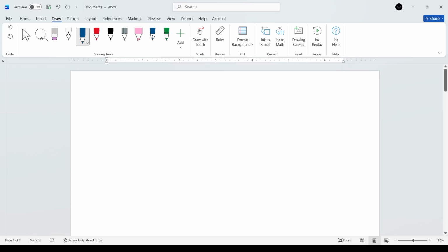I hope you can see the screen. We have a UDL, and then in the mid span we have 30 kilonewtons. We have been told that the UDL is made up of 5 kilonewtons per meter dead loads.